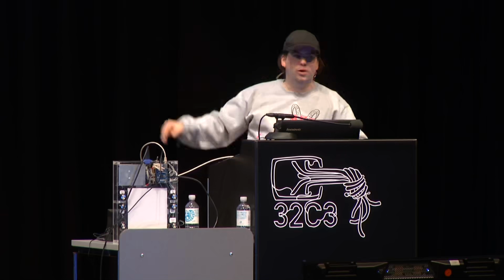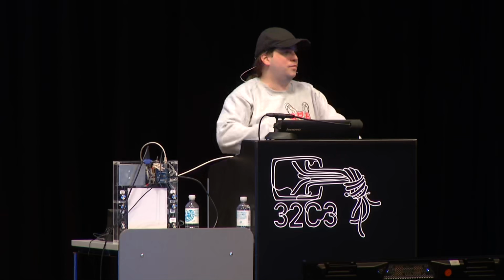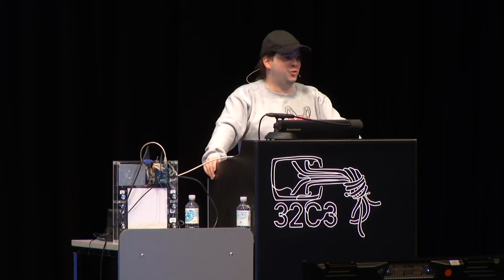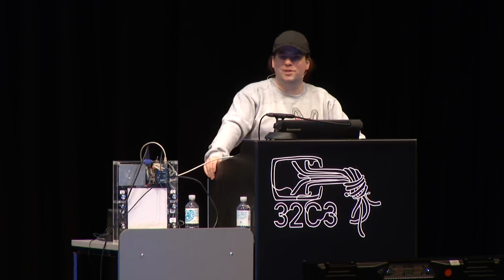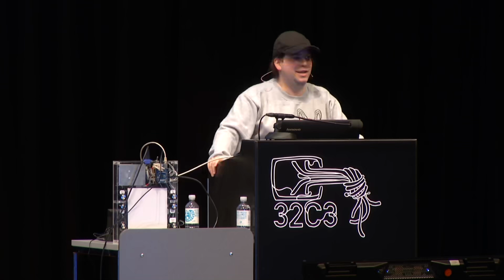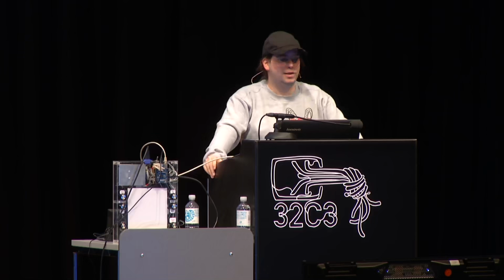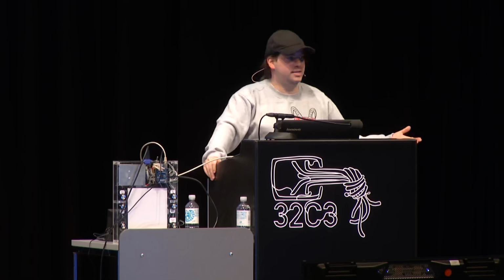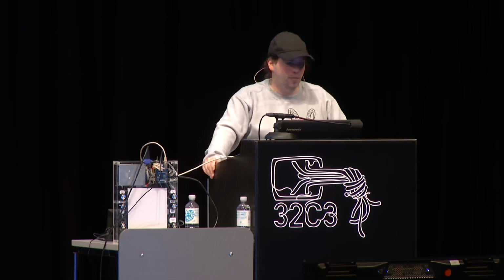The reason why we're always doing things on this low-level bitstream format is because we can create these files from our own flow, but we can also create them for the bitstream files generated by Lattice's flow. So it's very easy to verify if our interpretation of the bitstream is correct. We just create random Verilog designs, pass them through the Lattice flow, then convert the output back into something that is behavioral Verilog, and then use something like the formal verification features in Yosys to check if the Verilog we started with and the Verilog we got out at the end are formally equivalent.